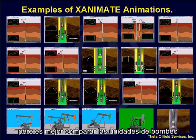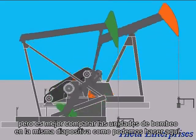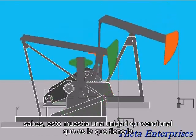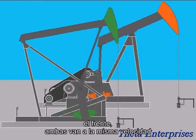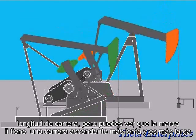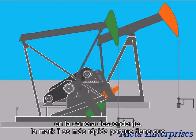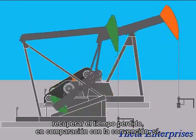But it's better to compare pumping units on the same slide, like we can do here. This shows a conventional unit, which is the one that has the orange head, of course, and the Mark II in the front. Both are going at the same speed, and they both have the same stroke length. But you can see that the Mark II has a slower upstroke and it's longer as compared to the conventional. But then on the downstroke, the Mark II is faster because it has to make up the lost time, as compared to the conventional.